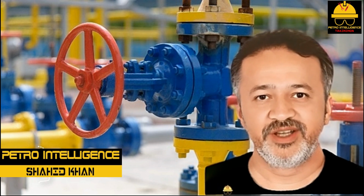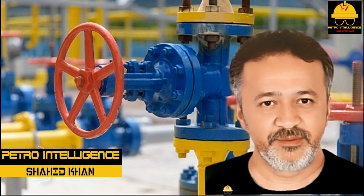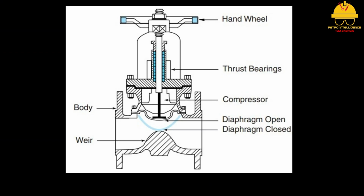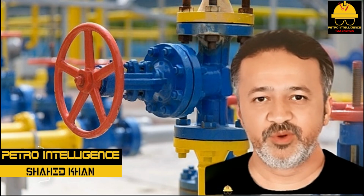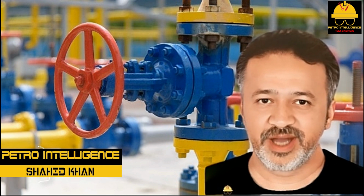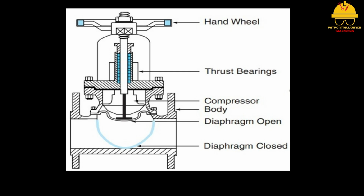The weir diaphragm valve has a weir or a dam located in the body of the valve as shown in picture. Fluid must go over the top of the weir and under the diaphragm in order to exit. There is a large pressure drop across the body of the valve. It uses thick, durable diaphragm materials. The non-weir, or straight-through diaphragm valve, has a flexible membrane that extends across the pipe as shown in picture. Pressure drop across the valve depends on the position of the diaphragm.